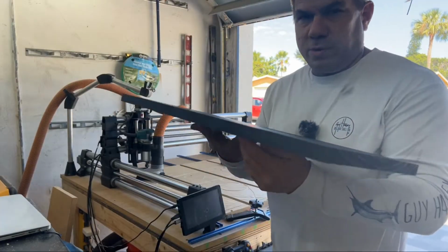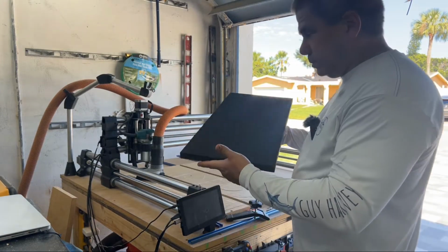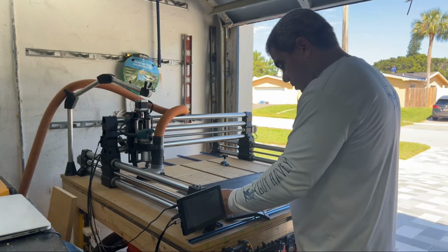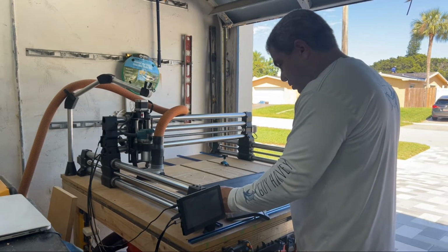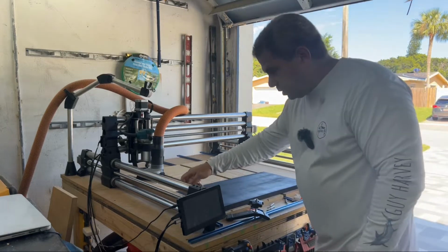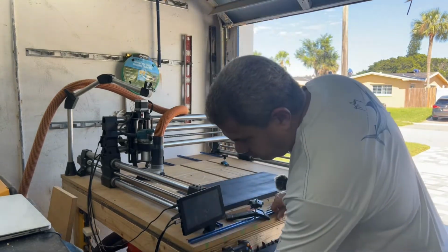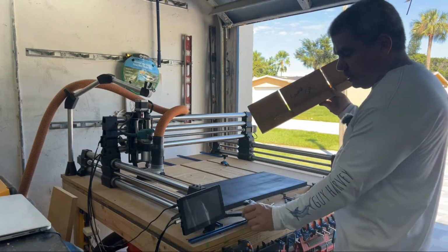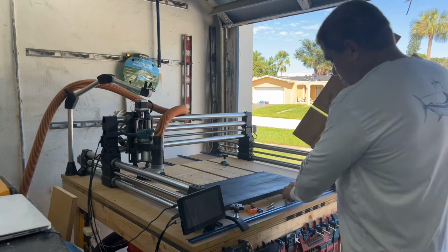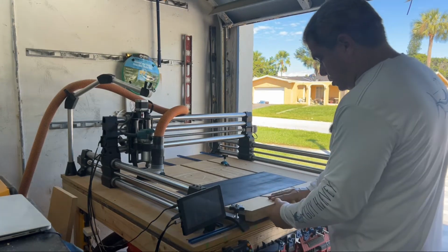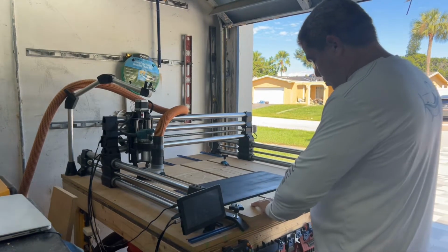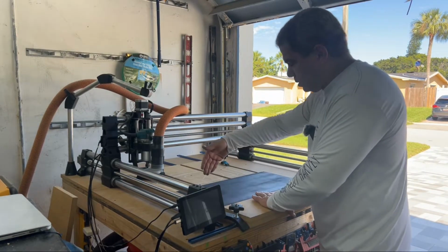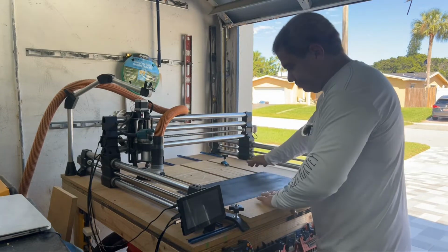Okay, and we're back. Got our piece of wood here that we're gonna use for this project. Right now, what I'm gonna do is clamp it to my wasteboard. I have a nice fence along here, makes it nice and square. I also have what I call my square jig. Because of the way I set up my table, I come over here and make sure my bottom is square and my sides are square, so that when the machine cuts it, lines are nice and square, my material isn't cockeyed.